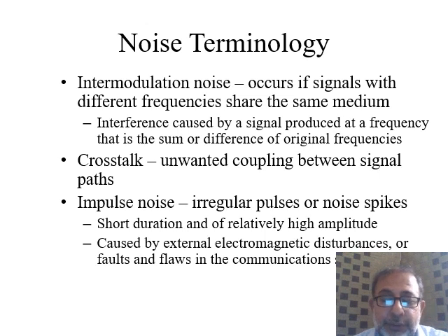For example, 2 into f1 plus f2 and 2 into f1 minus f2, similarly 2 into f2 plus f1 and 2 into f2 minus f1. Similarly, we can have 3 into f1 plus f2 and 3 into f1 minus f2. So many frequencies will be generated.